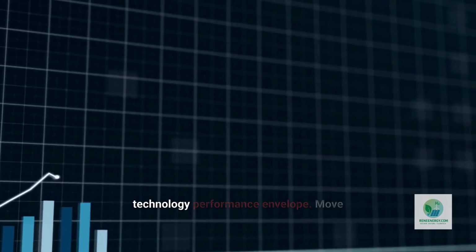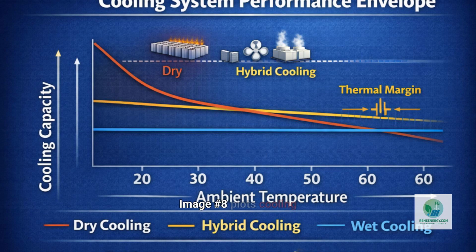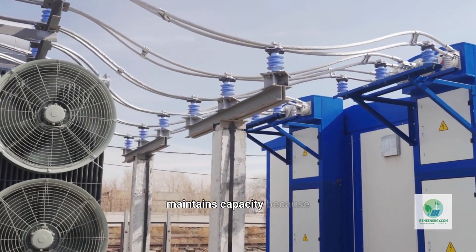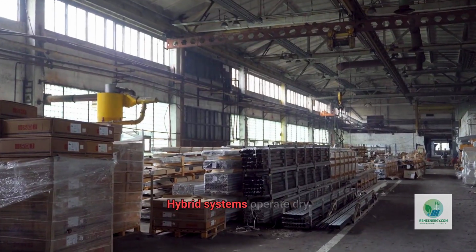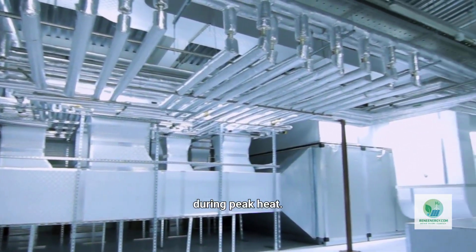Now examine the cooling technology performance envelope. Move to image number 8. Image number 8 plots cooling capacity versus ambient temperature for dry, wet, and hybrid systems. Dry cooling performance declines as ambient temperature rises. Above 50 degrees Celsius, thermal margin becomes extremely narrow. Wet cooling maintains capacity because evaporation depends on wet bulb temperature rather than dry bulb temperature. Hybrid systems operate dry under moderate conditions and switch to wet assistance during peak heat.